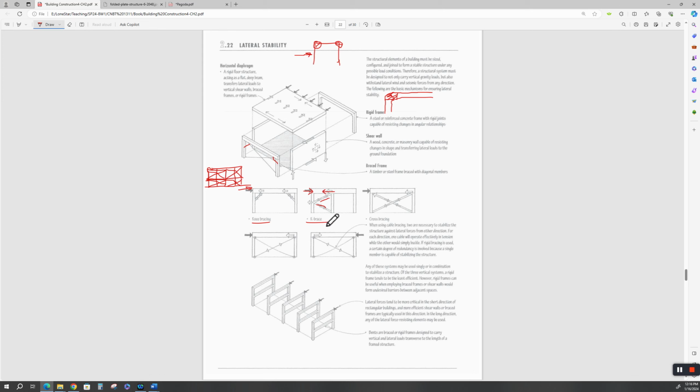Okay, now what happens with the K-brace? Well, we've just lost this bay. With a knee brace, we can still come in here and put a header in, depending on how high this is, with the wall framing, if we were going to frame this wall out. And we could put a window in here, right? There's a window opening. But if you're going to have an open frame, then knee bracing, in this case, gives you an open bay. K-bracing is going to eliminate a bay.